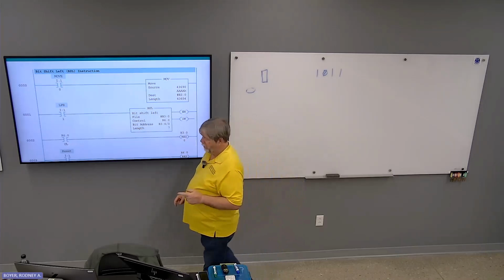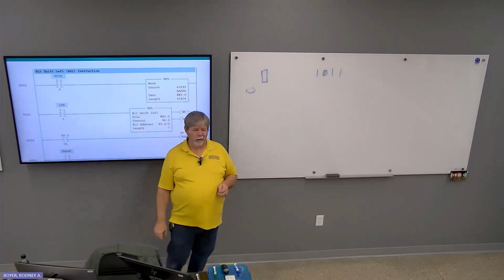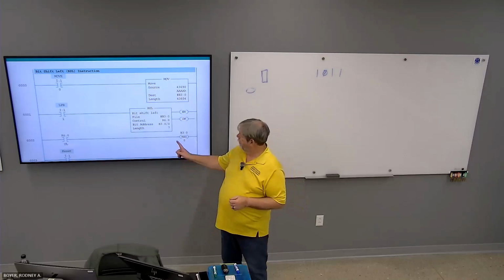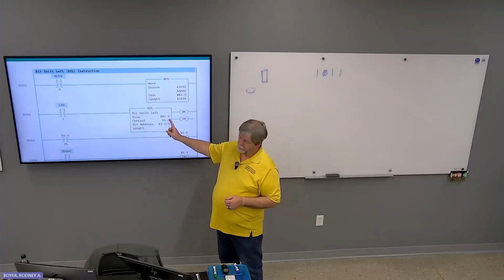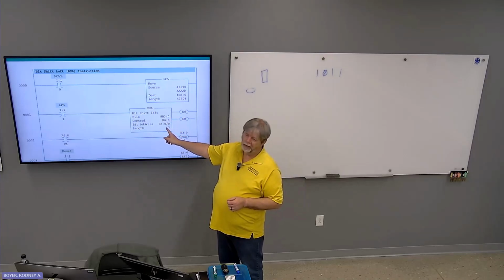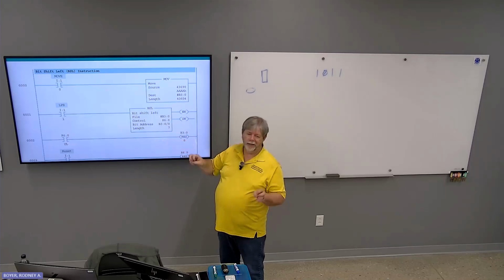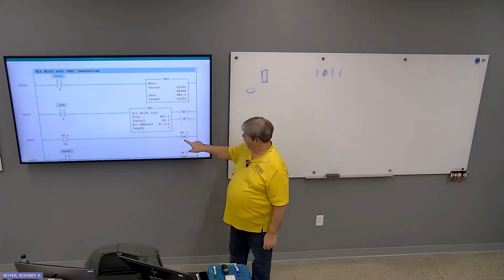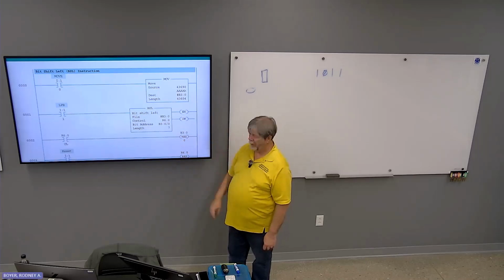The unload bit, though, is this /UL. When the bit in B306 moves into B307, that is the unload. That's what they're using to reset the bit file.